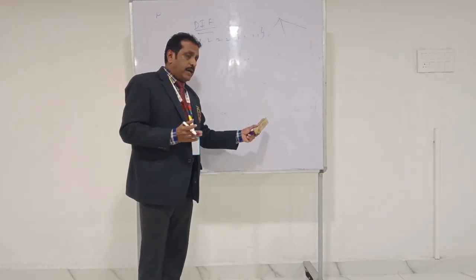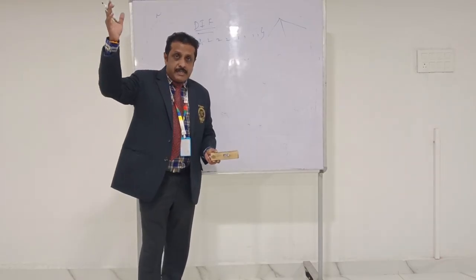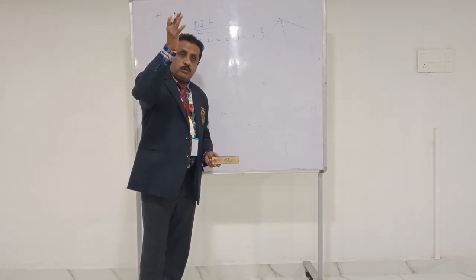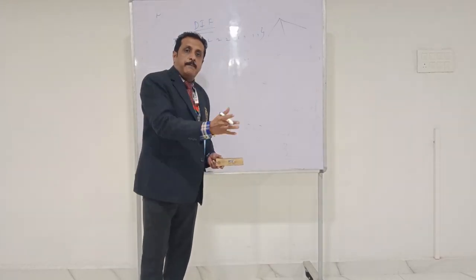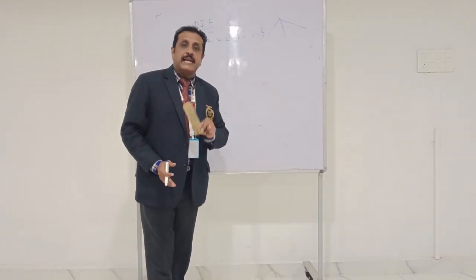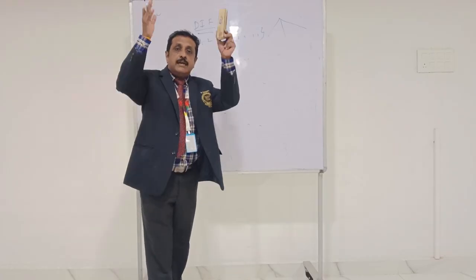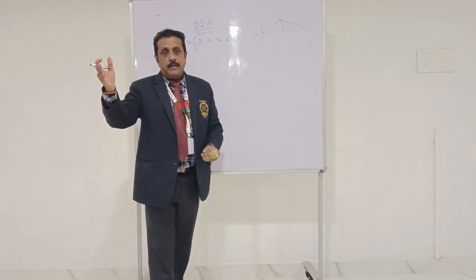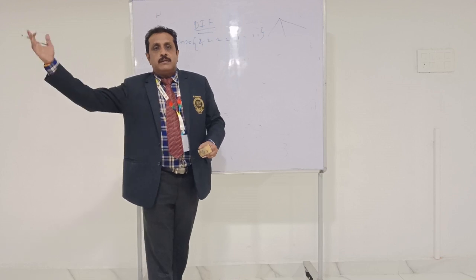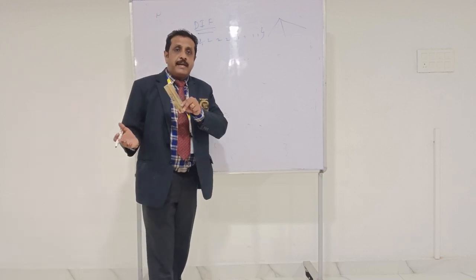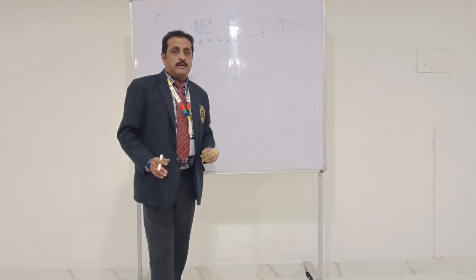What we see in DIT is the first stage of four 2-point, followed by two 4-point, and the third stage is one 8-point. Just reverse it and you will get the DIF algorithm. So the first stage is 8-point, followed by two 4-point, and the end will be four 2-point. That is the way to proceed with the DIF algorithm.